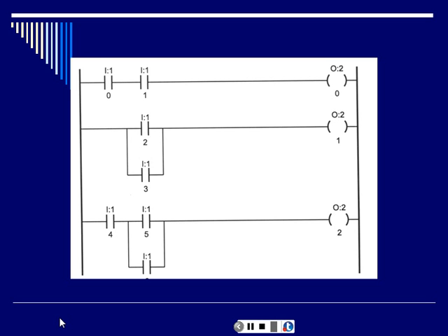No. Well, yes, but it can skip it. If it's not activated, it'll go down to the next rung. So it's not that you have to run one rung. It doesn't actually go one right after the other like that. It looks to see what will work and what won't, and runs what will work. So rung one doesn't have to work before you can operate rung two. They can run independently.